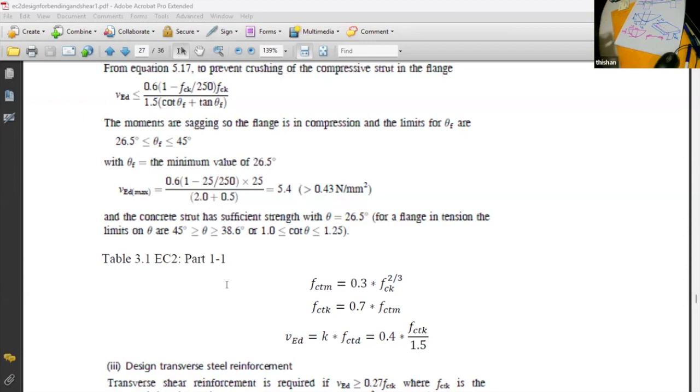provide any reinforcement. So that's what you generally find. But in the case of inverted T beams that we use for foundations, this failure can happen. So it's not a situation for general slabs. Slabs we are supposed to check, but generally when you check a slab it will be okay. If that is the case, what is the solution? Better write a spreadsheet so that this is checked automatically, because this is just a useless calculation for most of the slabs. But you have to get these moments fed.